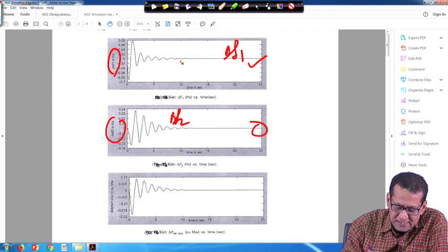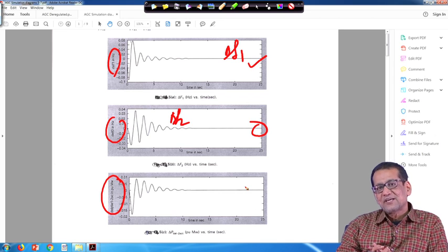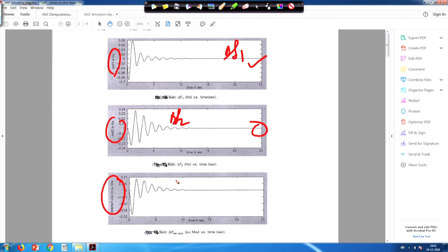Similarly, this is your delta P tie 1 to actual. What happened here for this case is that the distribution companies in area 1 actually demand power from the GENCOs of that same area, right. So, there is no question of actual tie line power flow. The scheduled tie line power flow will be 0, and that is why the actual and error will give identical response.